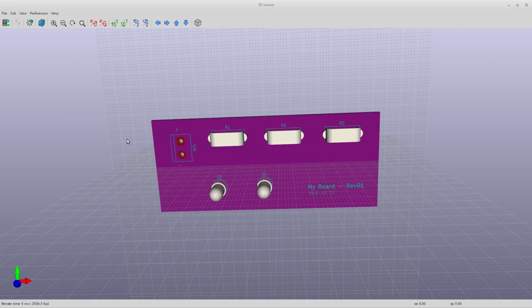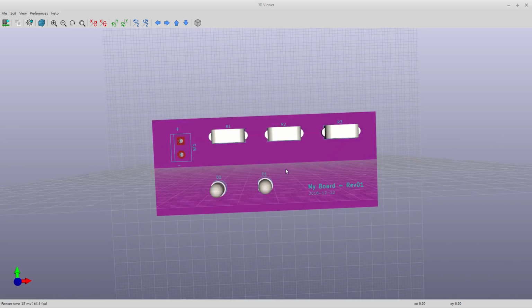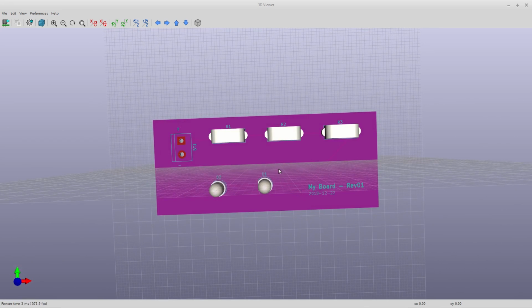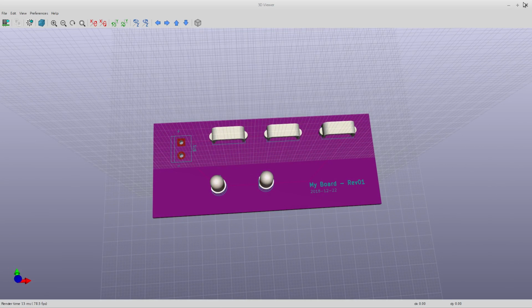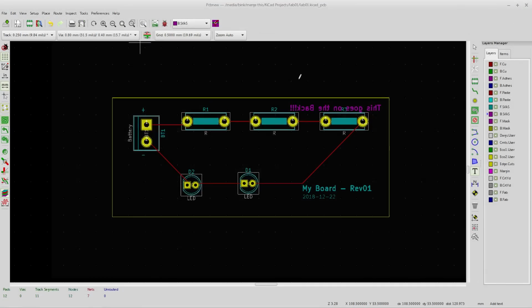If you're really slick, you can even import a picture. You could take a picture of some sort, turn it into, it's kind of got to be a monochromic type thing as you could imagine, but I could even see that you have like a little baby version of a sine wave right here that at TP2 you should be seeing a small sine wave of so many hertz. At TP3 it should be rectified and maybe you're seeing part of it and somewhere else it might go through an ADC or something like that and you end up with some kind of other square wave. So yeah, you could design all of that into it if you felt like it.